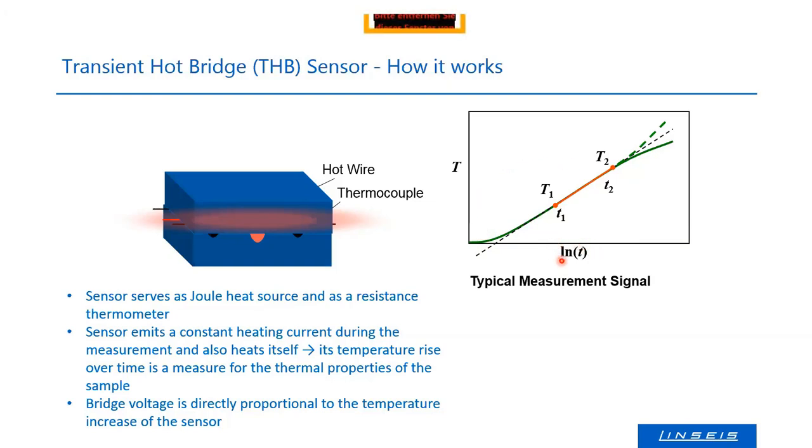When we scale the time axis logarithmically, we get a linear part of that curve, and we can use that to calculate the thermal conductivity.